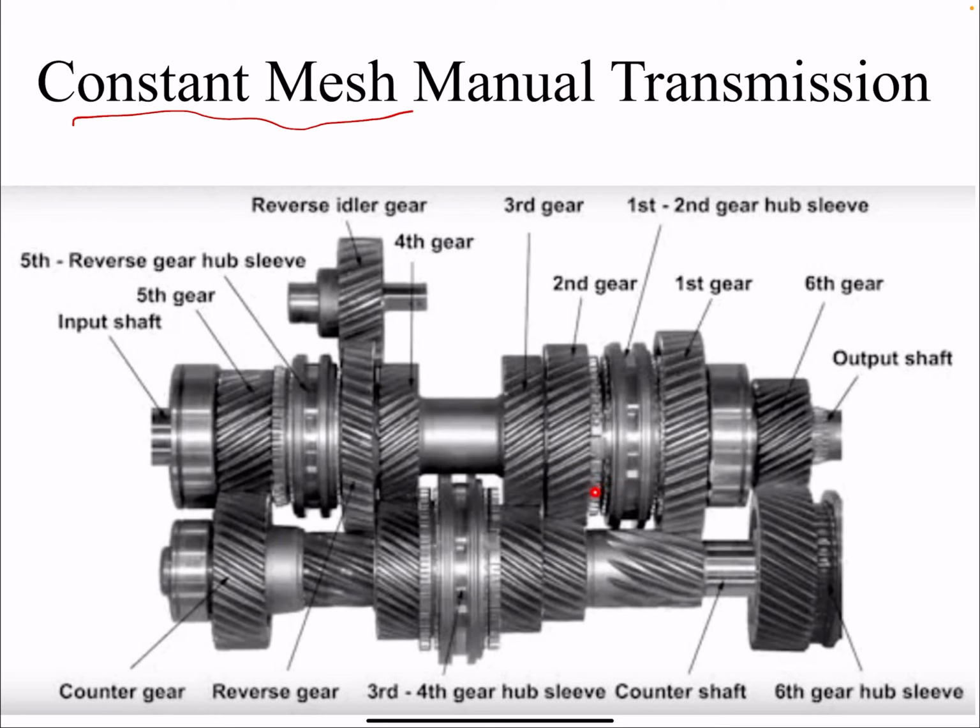And then you have it for the fourth, this is for the third gear. Again, you're going from the smaller one to a larger one, so still we are reducing the speed and increasing the torque. If you go to the fourth gear, it's almost identical, which means that you can connect input and output directly. Gear 5 is the gear where you are going from a larger one to a smaller one, and again, it's not much. So you're decreasing the torque a little bit and increasing the speed.